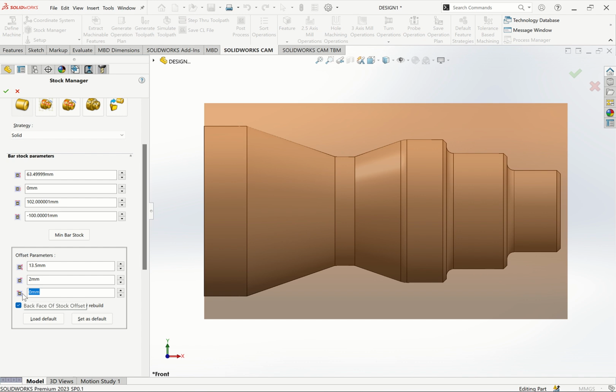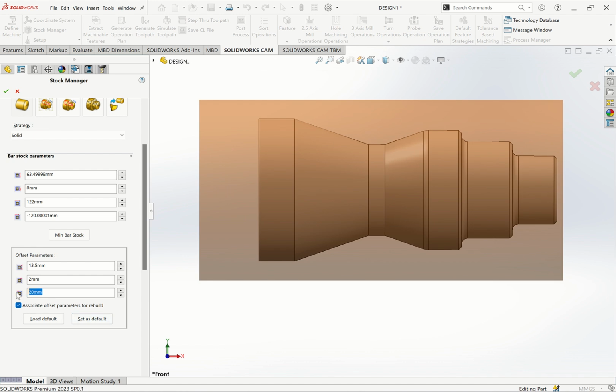For clamping purposes, where the chuck would be, I can maybe put 20. You see how it updates itself. If I put 30 and then I click anywhere here, it updates itself. So this side up here is my chuck, where I'll put my chuck. Then this side where I'll do facing. Then the upper side where I'll do my turning. So the blank side, you are saying, is the stock.